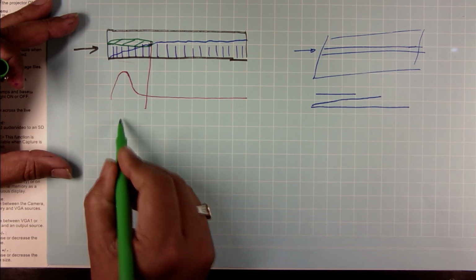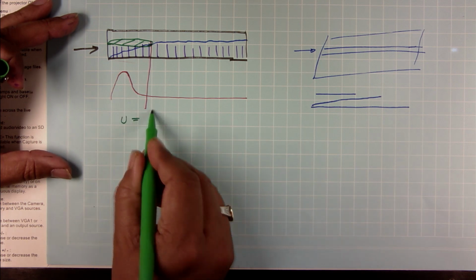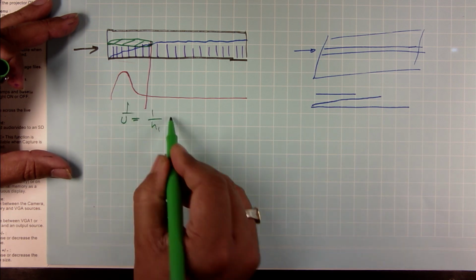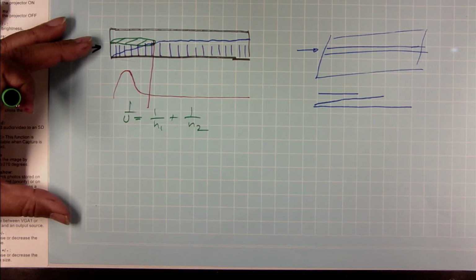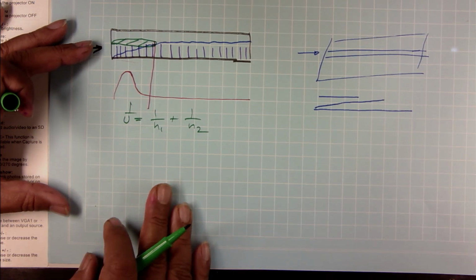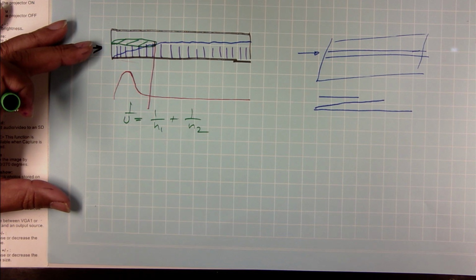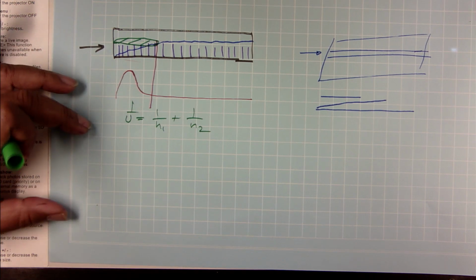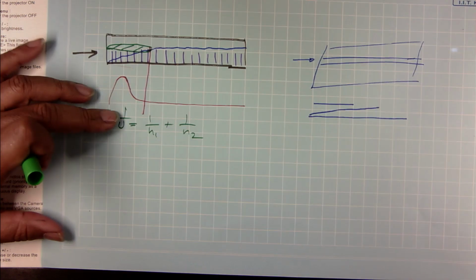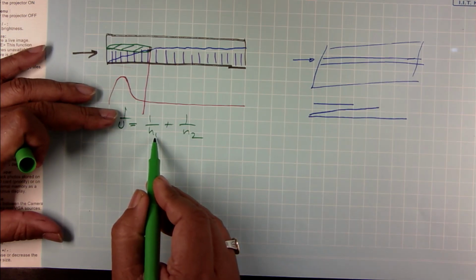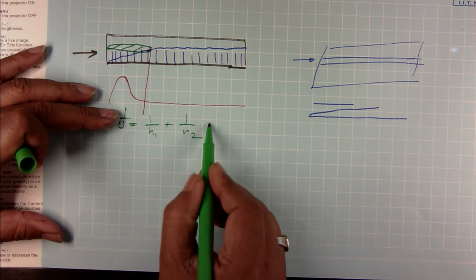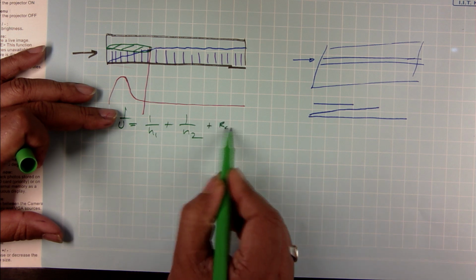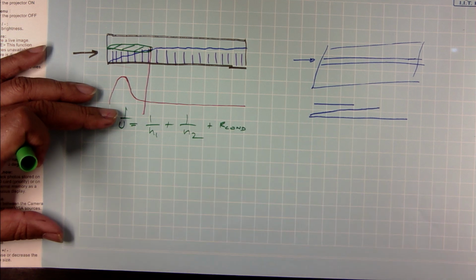goal was the overall heat transfer coefficient, which is 1 by H1 plus 1 by H2, right. If you have heat transfer between two flowing liquids on one side of a solid, that is your heat exchanger principle, right. So the overall heat transfer coefficient depends on the heat transfer coefficient on the hot side and on the cold side of your flow, plus of course the conduction resistance of the metal layer in between, but this one is usually neglected.